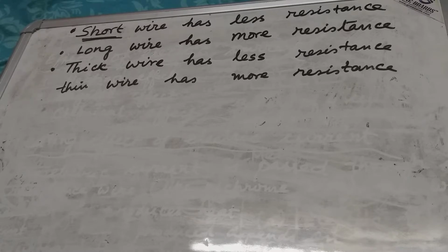So nowadays, what we are using is CFLs, that is compact fluorescent lamps. Why are we using them? To reduce or discard the huge wastage of energy which earlier was happening in electric bulbs. Why was it happening? Because a huge amount of current was getting used up in heating, and very little was used in lighting the bulb, which is not at all desirable. That's why came the fluorescent tube lights and compact fluorescent lamps, which do not work on the heating effect of current.